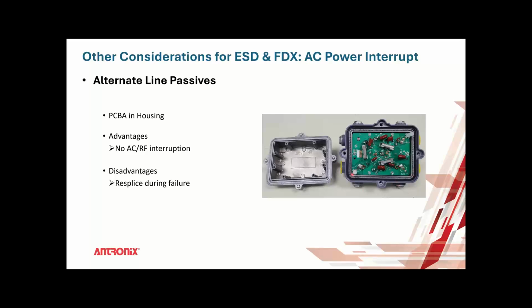We do have a product here that has some features that allow this to be replaced in the field. These are captive screws. There are these little handles here. You could pull this faceplate out and press fit another faceplate in, so you don't really have to resplice in this product. But you've got to keep in mind, if you have certain versions with faceplates in the cover or in the housing, as you remove those faceplates, you could have AC interruption and reboot your RPD nodes.